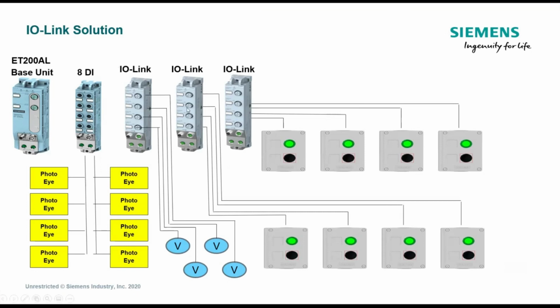So typically it's like a cluster, where you have a cluster of devices, and to get to that cluster you're going to have a field bus drop in the center of that, and then the devices will span out in say a 60-foot radius from that drop. If you had more of a conveyor where you really want to daisy chain them down, you're going to use that field bus to get them farther and then drop the master where you need the devices.